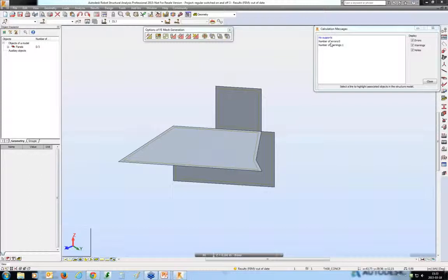If you do that for two neighboring panels, it may happen that at the common edge you have two overlapping nodes, each created during the generation of the meshes for each of the panels respectively. It is at the stage of model generation that these two nodes are actually merged. So maybe that's the reason: if model generation was not performed, you actually have two separate nodes and an incoherent mesh is reported.